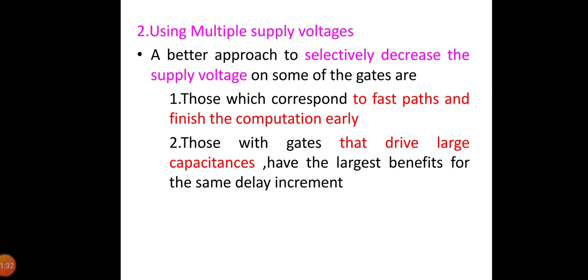If a gate supplied by VDDL drives a gate at VDDH, then the PMOS transistor never turns off, resulting in a static current and reduced output swing. A level conversion performed at the boundaries of the supply voltage domains prevents these problems. An asynchronous level converter is based on the DVSL template, similar to the low-swing signaling gate, and the cross-coupled PMOS transistors perform the level conversion by using positive feedback.